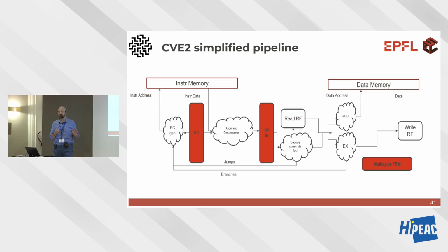They don't waste cycles. Taken branches, very bad. I waste 2 cycles. I'm betting on that. Is it good or not? No idea. But it's smaller. This implementation is smaller, consumes less power. My goal is not performance, right? If I waste one cycle on a branch that I run 1% of my time, because most of the time I'm sleeping, I don't really care, right?